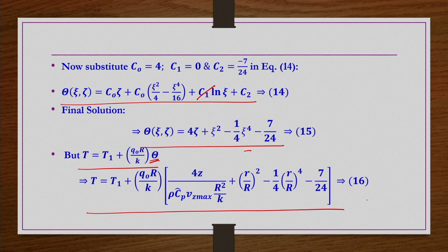Alright. So, this is the temperature distribution for a Newtonian fluid flowing through a pipe, but the flow is under fully developed flow conditions. The temperature profile is also valid for only the fully developed region, not valid for the entry and exit regions, valid for only the fully developed flow region. If you have to include the entry and exit regions also, then you have to use a numerical solution; otherwise it is not possible to get approximate solutions like this.